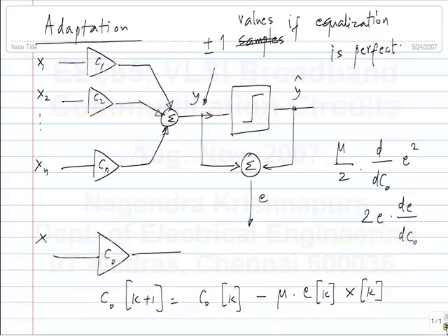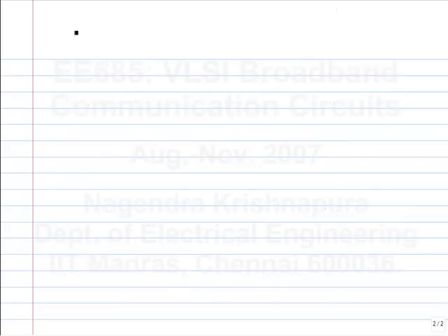But you don't expect really rapid changes and expect adaptation. So using a small value of mu is safe because it will always converge, but it will become slower to adapt. So in case of an FIR equalizer, I'll show it as though the input itself is in discrete time. So this could be, let's say, the output of a sample and hold in a receiver, and so on.